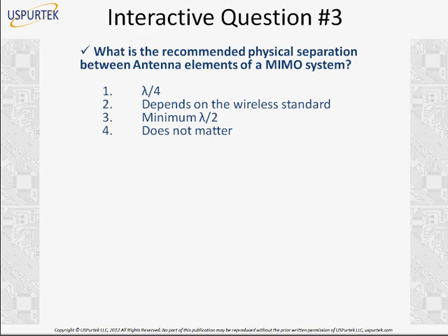We have seen that if we reduce it to less than half wavelength, what happens? It becomes a reactive system. It no longer remains an antenna system. A reactive system which could be inductive or capacitive, and it becomes more like a transformer then.